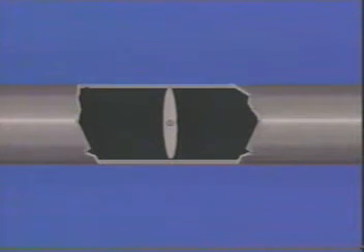Water hammer is another effect of fluid forces that must be considered. In some process operations, water hammer can occur if a valve suddenly slams shut. The force generated by the pressure surge can result in piping failure or damage other process equipment.